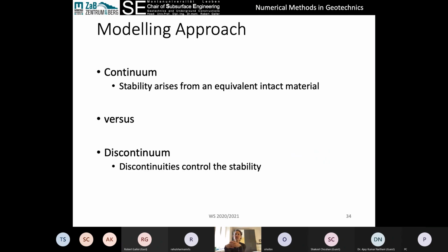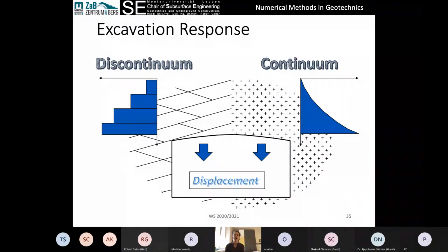So nowadays, finite difference, finite element, those are mathematical aspects of the code, but from a functional perspective, as an engineer, it doesn't really matter whether you're using finite element or finite difference. So some of the bigger considerations then are having to do with the different types of models rather than the solvers that they use. So two of the most commonly discussed types of models will be continuum versus discontinuum. Which one do you pick? So let's have a look at how each of these are formulated.